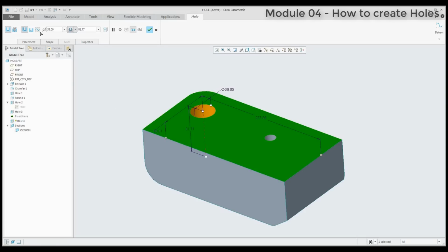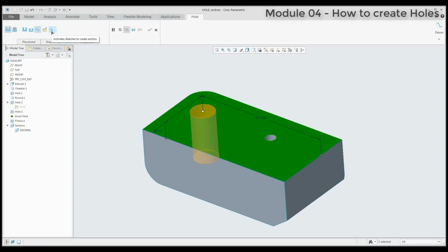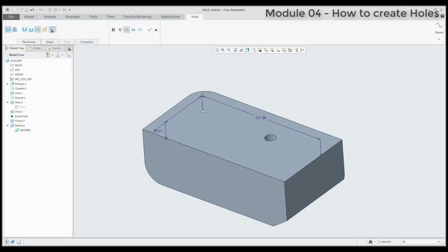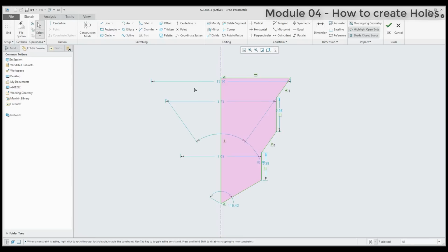And then over here is the small icon, use sketch to define drill hole profile. If you select this function, you can jump to the sketch, and the system will allow you to create a center line, and then you can create your custom shape of hole. So for example, I'd like to create a shape like this. Don't forget that you create something like a Revolve feature.